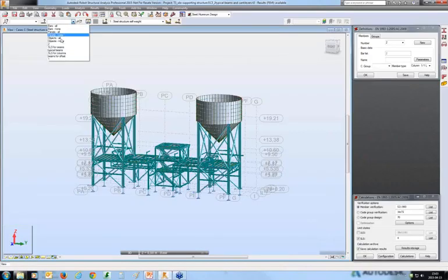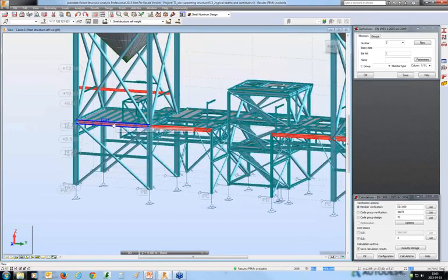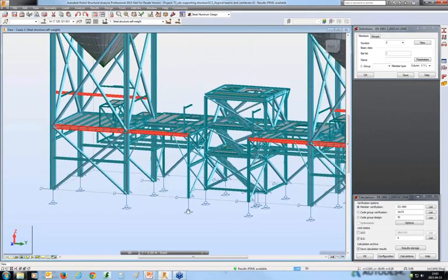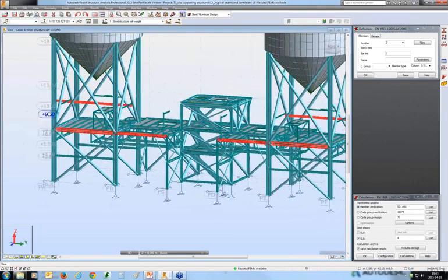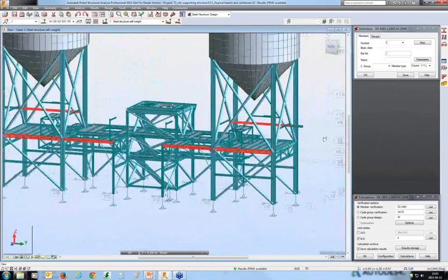Okay, let me select the group of beams, and if you have a look, I defined these beams from column to column, from the support points to the support points for monorails, and cantilevers being separate elements. So okay, let me exclude cantilevers for a moment from the selection because we'll focus on them later on. But for such a selection, I can create a new design group